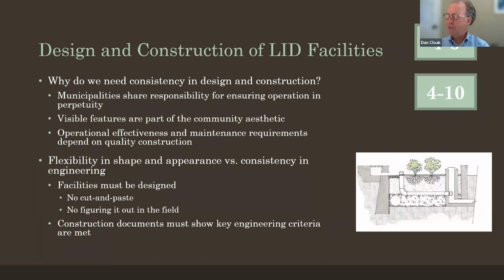Probably the 4% sizing factor is an important piece of it, but maybe not as important as always having flat, always having the sand compost mix, always having class 2 perm with very few exceptions as the base layer, always having all the layers flat and the interface with the native soil ripped, having a concrete catch basin style overflow rather than an upturned plastic pipe.